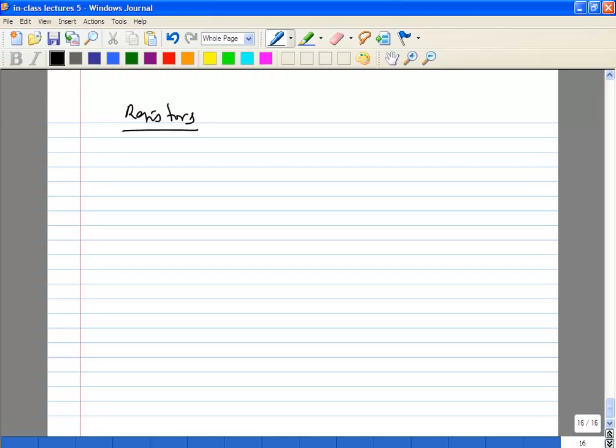So let's look at the different kinds. Polysilicon resistors, whether silicided or non-silicided, will typically have very small values. Obviously the lowest values will be your metal routings themselves. They'll give you up to probably a few ohms. These can probably give you a few tens of ohms.